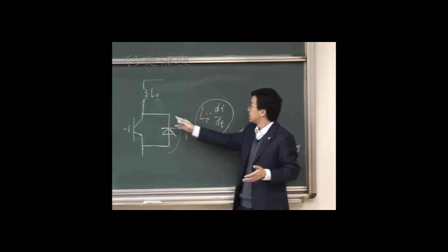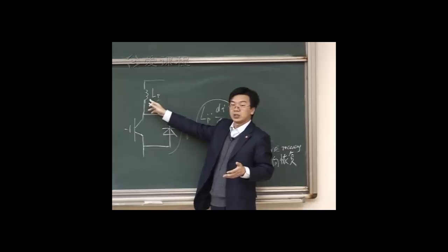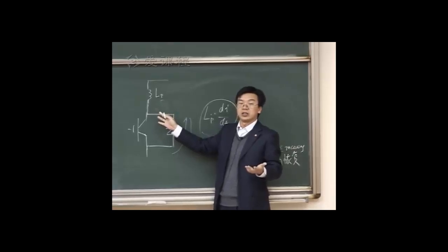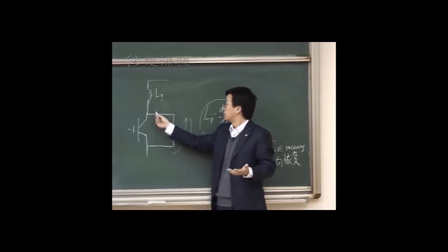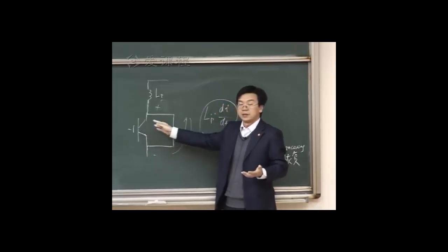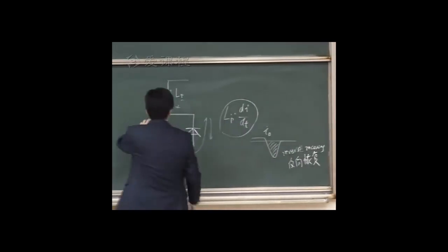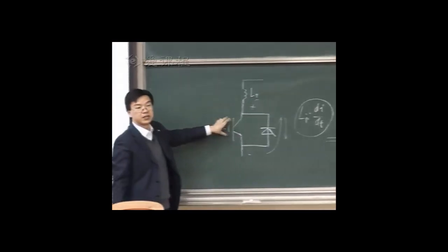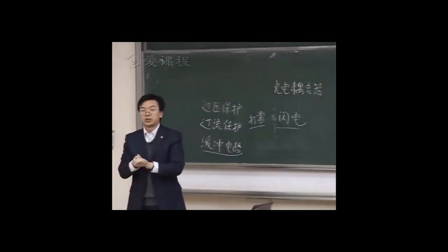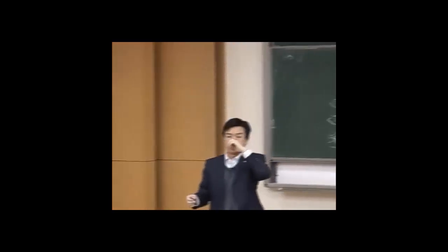And that high di/dt, together with this wire parasitic inductance, will also cause high voltage. Okay. That high voltage will be generated across the anti-parallel connected IGBT or power MOSFET. Those are the two basic reasons for internal causes of overvoltage.